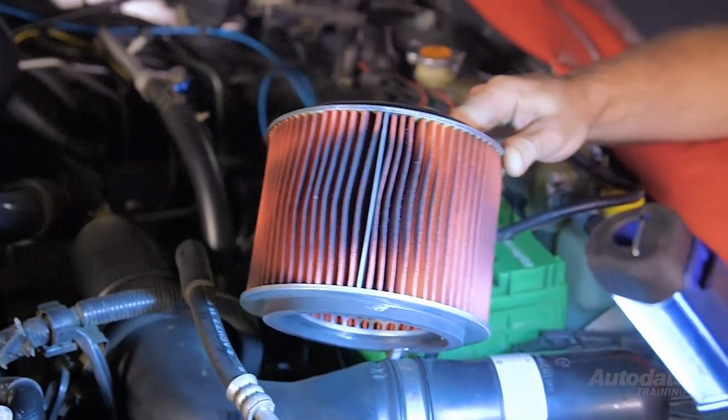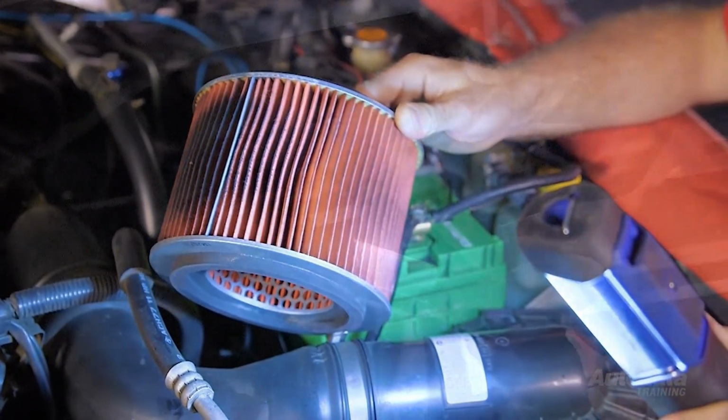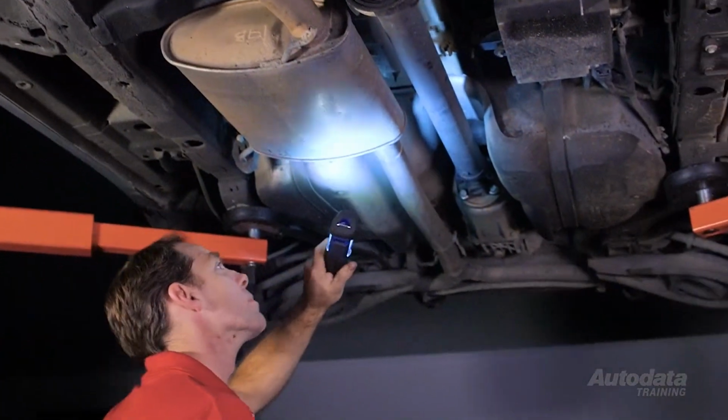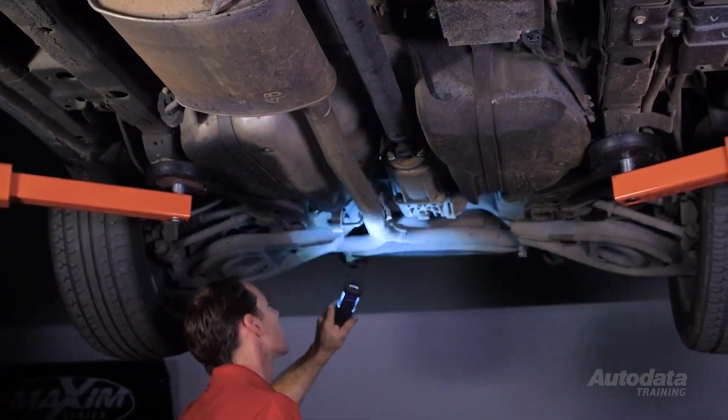Inspect the intake system for any restrictions to airflow. Inspect the exhaust for any damage or restrictions that may impede gas flow. There are three common types of ECM controlled systems: solenoid over diaphragm, direct acting solenoid, and servo motor controlled. They each require different testing methods. We'll look at them one at a time.